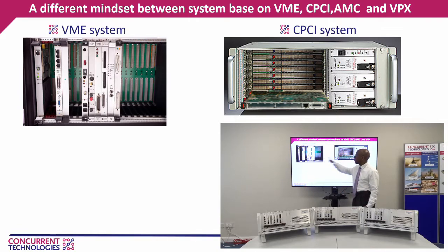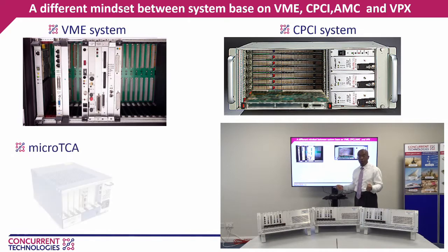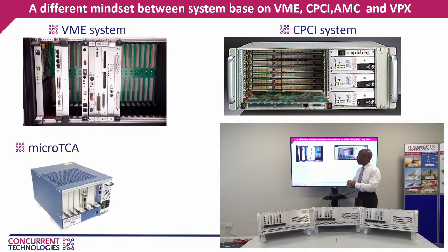Now, with these two legacy technologies, the data bus and address bus go to all the slots, and that's why it was very easy for them to use any board in any slot. The technology moved on, and to increase the bandwidth between slots, this has all been serialized. So you end up with something called serial fabric, where you have point-to-point communication. And this has also been used in backplane type technology.